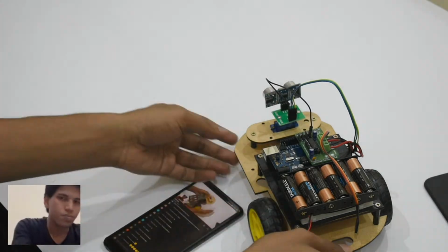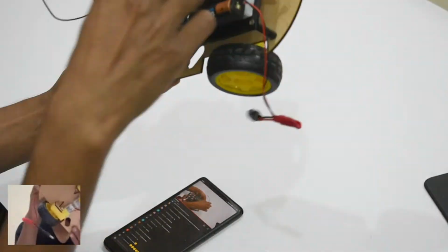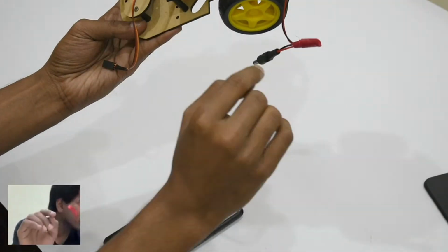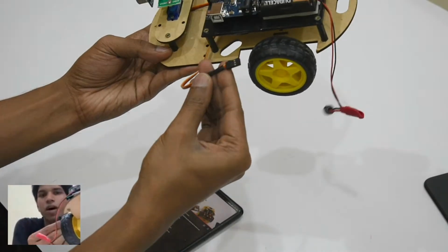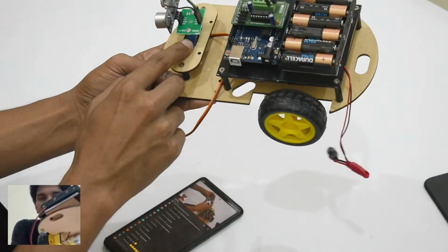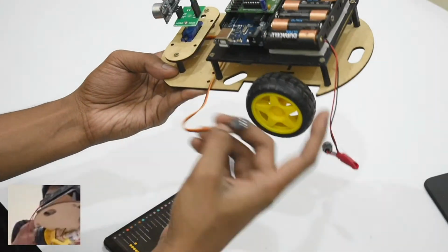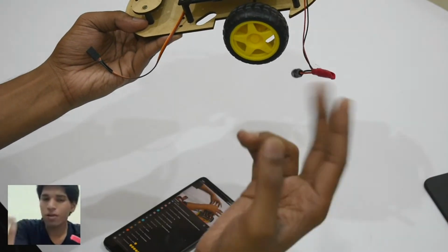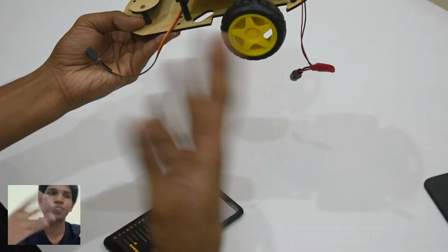Now once we have done this, we have to connect our servo motor and our ultrasonic sensor to our Arduino. That's all we need to do. The servo motor has 3 pins. One is the data pin that tells how much angle it has to rotate, and the other 2 are power pins. Everything electronic needs at least 2 pins, one positive power supply and one ground, and other than those 2, it will need some more data pins or read or write pins.